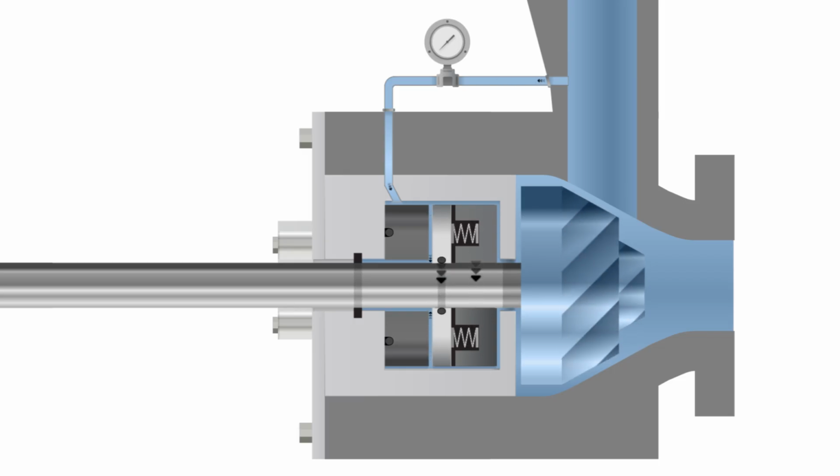In this example, the separation fluid is introduced through a flush system onto the seal. The separation fluid then circulates through the seal, providing lubrication and cooling before exiting through the seal housing into the pump. The sealing process reaction may also create a build-up of solids on the atmospheric side that need to be removed to ensure the seal remains contaminant-free and the seal faces don't become damaged.